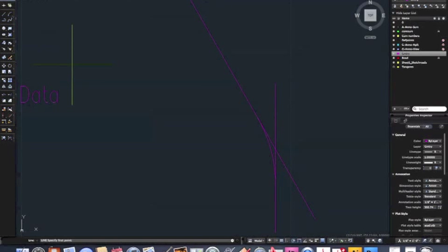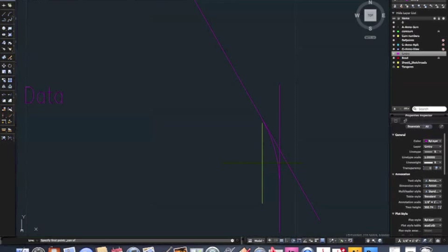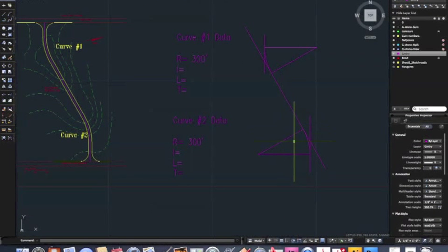So that's kind of a useful thing to get in the habit of. I can do that down here to locate the center point of this arc. If I did L, enter, hold down shift, right click, and center, and there, it snaps to the center point of that arc. Once you click that one, it goes ahead and unlocks from that. So I'm just going to trace these to the endpoints of this arc. And we have our interior angle essentially denoted.